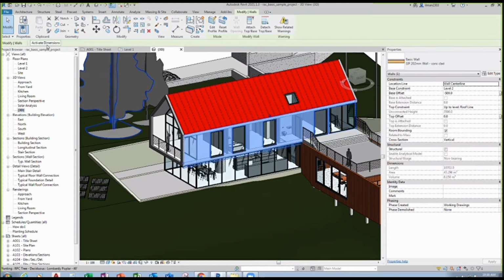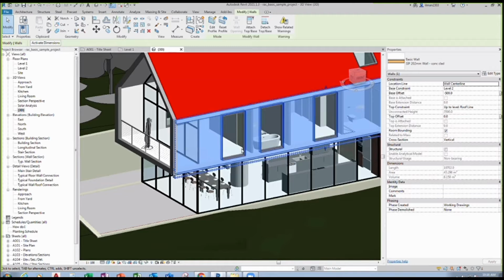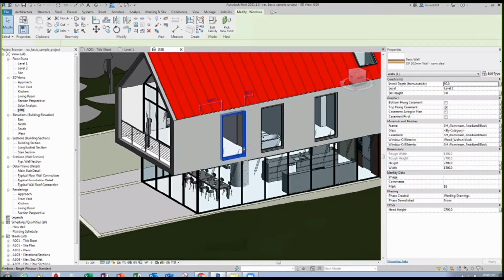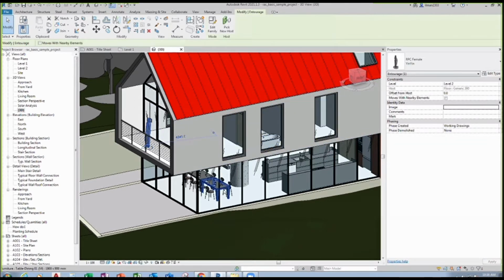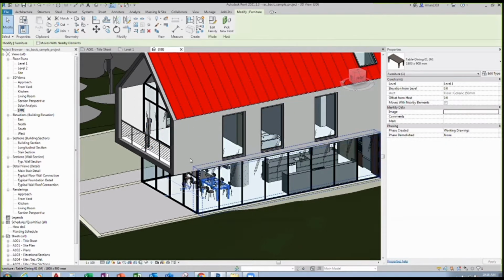maybe you want to edit that dimension, or maybe like families. So there are some tools, maybe in structure, you will understand more about this. You can edit the height and the depth or something like that. You will be right here. But usually we will edit at the properties palette.